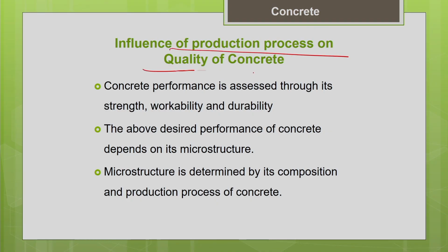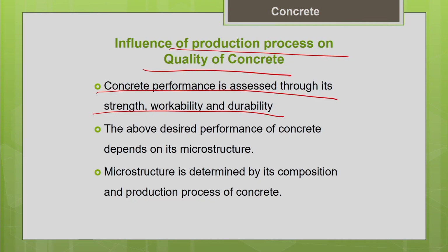One important thing to be noted is that the production process has a significant influence on the quality of your concrete. Generally, we assess the performance of the concrete in terms of its strength, workability and durability. You can get your desired performance provided your concrete has the desired microstructure. All the strength and durability depend upon the microstructure of the concrete.